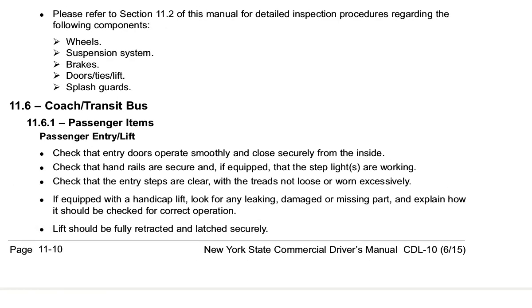11.6 Coach Transit Bus Passenger Items, Passenger Entry Lift. Check that entry doors operate smoothly and close securely from the inside. Check that handrails are secured and, if equipped, that the step lights are working. Check that the entry steps are clear with the treads not loose or worn excessively.